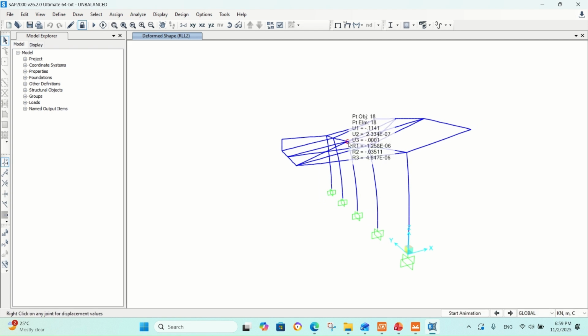Now we can see that the value of the column drift dropped from 160 mm to 114 mm. The deflection dropped to 189 mm. So there's a big change in the values for deflection and drift.